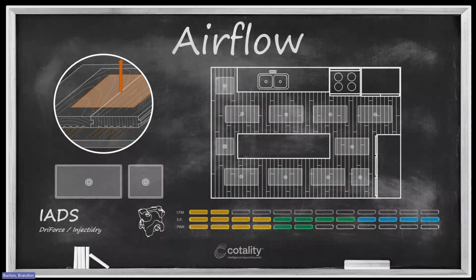Now, between the mat's short sides, when I go from one mat and move across perpendicular to the next mat, so the two short ends of those mats, that distance never needs to be more than about 2 feet apart, because the air is not moving nearly as much in that direction, since that's opposite of the direction of the flutes.